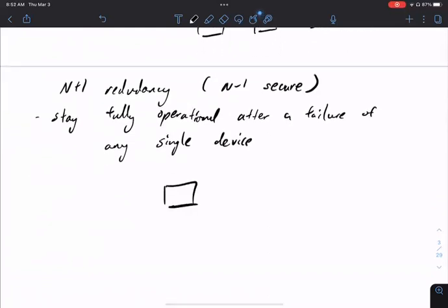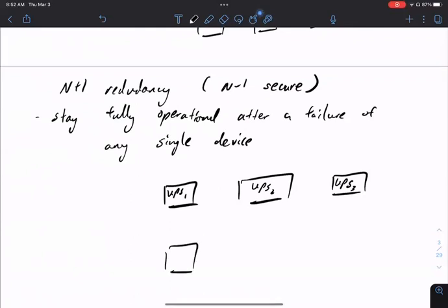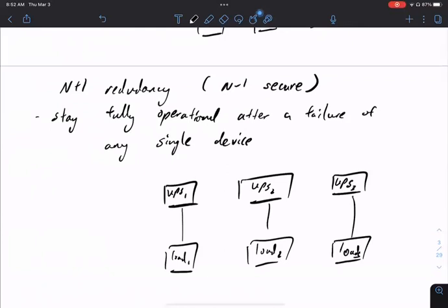For example, let's say you have 3 UPS, and you have load. This is, let's say, a standard connection. This is a typical, close to realistic layout inside the system. I don't have to connect to every one of them, but in this case you can take out any of the UPS and I still have backup. So this is called an architecture layout.